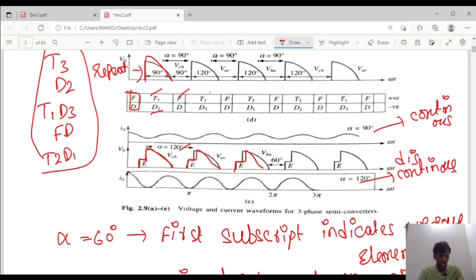For each period cycle of 120 degrees, V0 is seen to have three components. When the SCR is gated, the thyristor and diode will conduct for 60 degrees, and V0 reaches 0 and tends to be negative. So the freewheeling diodes get conducted and hold the load voltage at 0. All the energy stored in the inductance can be discharged through the freewheeling diode.